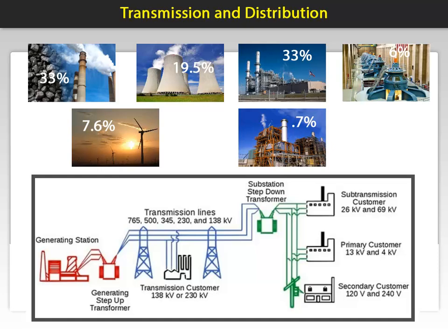At this point of the journey there may be a large industrial facility with a high electricity demand, such as a manufacturing plant, chemical processing facility, or a large data center, that purchases power at 138 or 230 kV. As the transmission lines continue to move the power, they can connect to a substation which utilizes a step-down transformer highlighted here to drop the voltage as required by the customer and sent over distribution lines highlighted in green here.